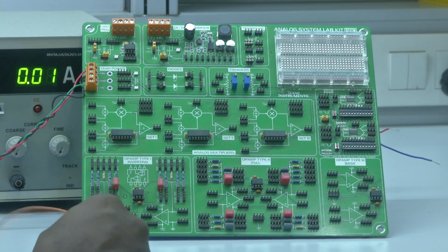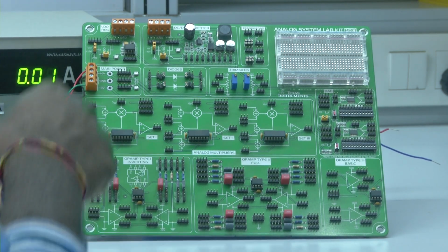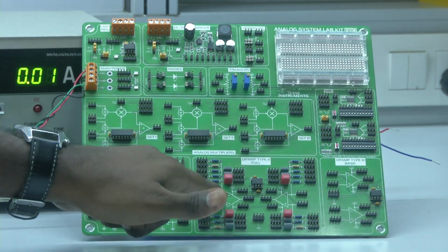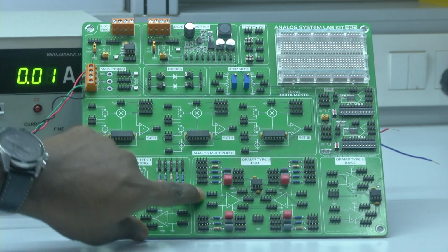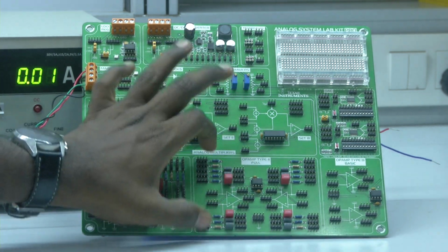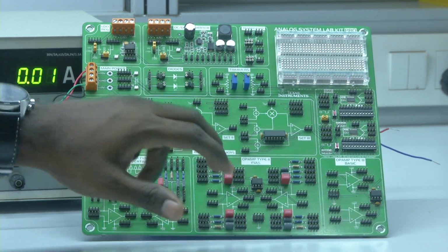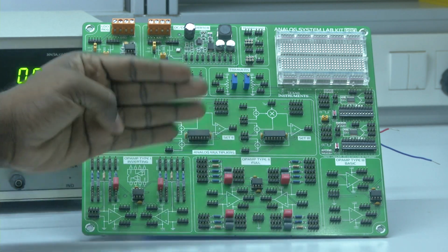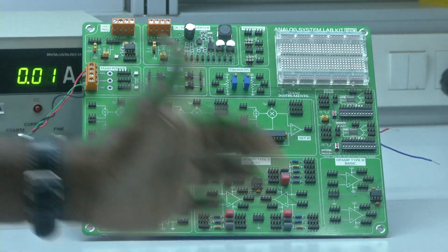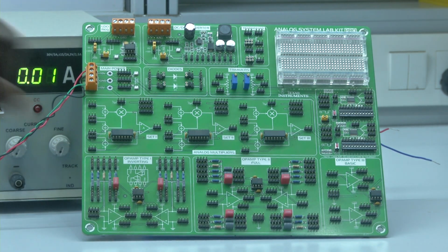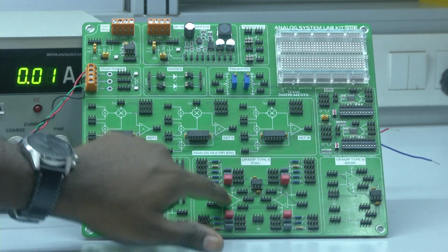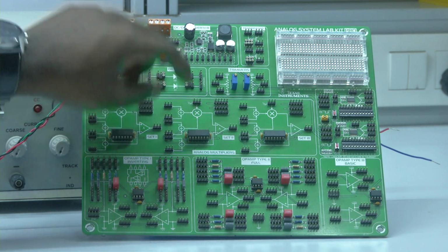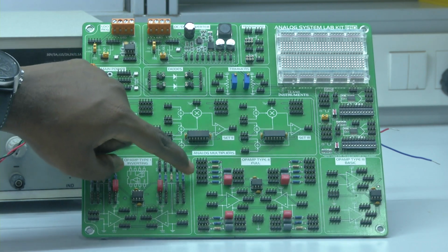If you observe here, the input has to be provided through 1K. If you carefully look at the inverting terminal, one end is connected to OPA2A in. OPA2A indicates this is the second subsystem of the operational amplifier type. A indicates, since it is a dual op-amp, it is divided into A and B: channel A indicates the first operational amplifier, B indicates the other operational amplifier. So, to the negative terminal, along with that, it has provided fixed resistances. The resistances they have given are 1K, 2.2K, 10K, 4.7K and 1K.